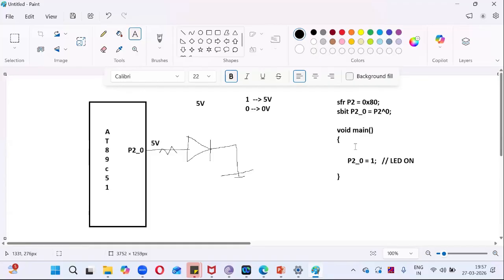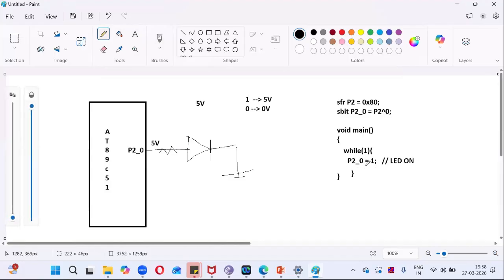If you want to run your LED for infinite times, there is a loop called while(1). So you will write the program under while(1). For that reason, in bare metal programming, all the code is under while(1), so that it will run for infinite times. This is the first concept in bare metal. In bare metal, whatever program you write goes in one infinite loop. So while(1) is the best option for an infinite loop. For that reason, whatever program we write goes under while(1). Clear, everybody? Yes.